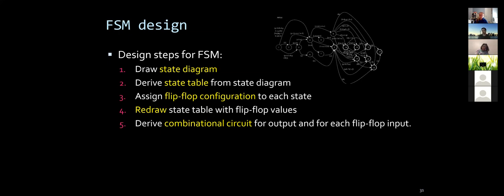There might be some manipulation with the inputs and outputs to get the right results at the end, right? But that's a combinatorial circuit. It's so simple, and that's it. That's the last step, where you already have all the parts of your output. You just need to merge it into an AND or some simple combination of the output. Okay, that's pretty much what your finite state machine design is and how it can help you build the actual circuits.